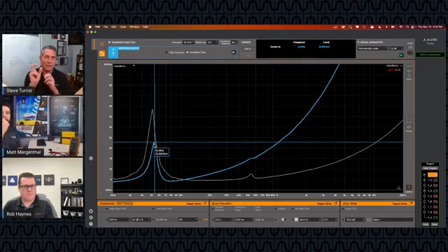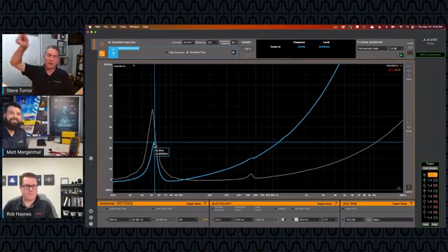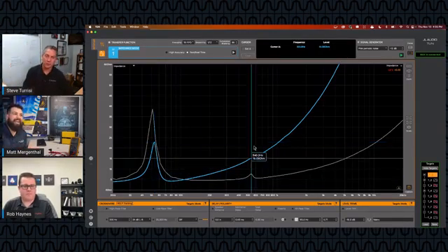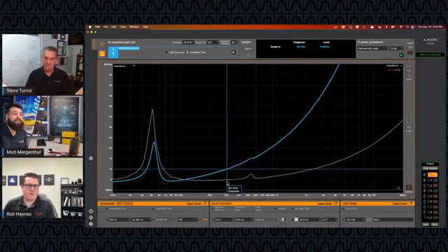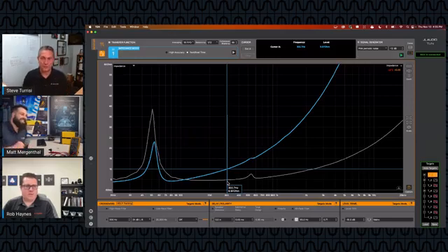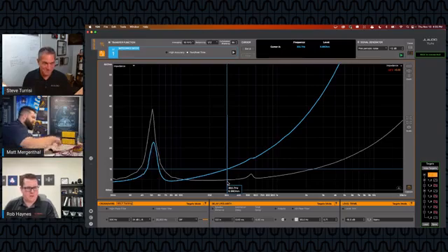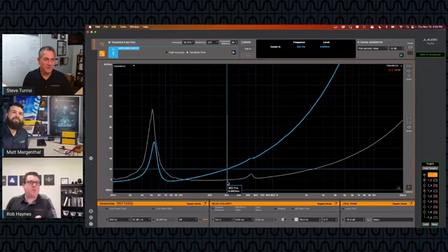And for the record, the coil on a TW3 is pretty massive, so that's why you see that rise at those higher frequencies. TW3 is not going to play 5K very effectively. It doesn't play 300 very effectively. Right, exactly. That's one of the reasons why. It is cool how with the size of the coil and that increase in inductance, we can see how the driver itself has that natural almost crossover built into it.